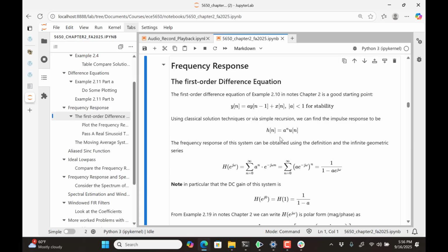And guess what they're synonymous with in the analog continuous time domain? The RC low-pass filter. They're that same exact shape. It's the discrete time version of a low-pass filter, but if a happens to be negative, in this case, it can be a high-pass filter. So it's kind of cool the way that works out.